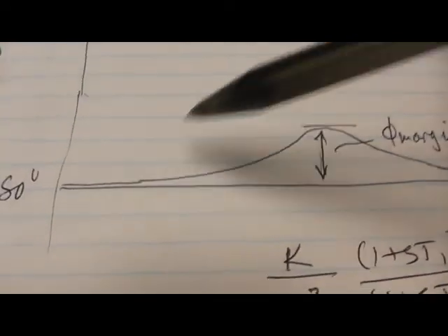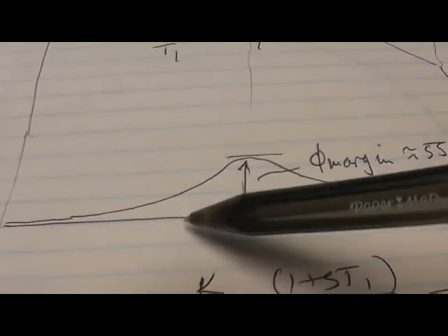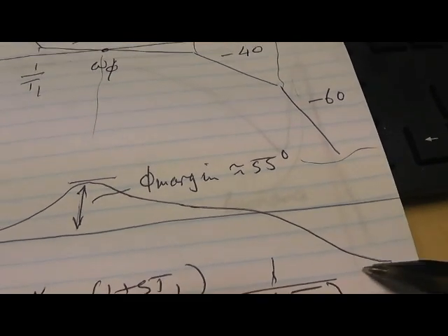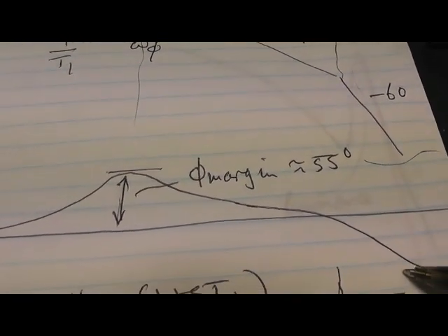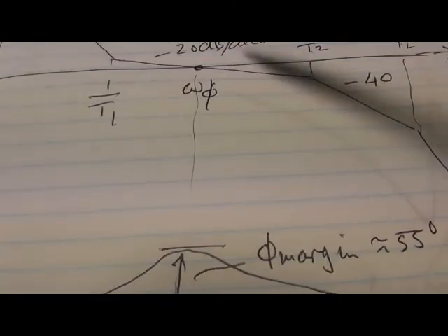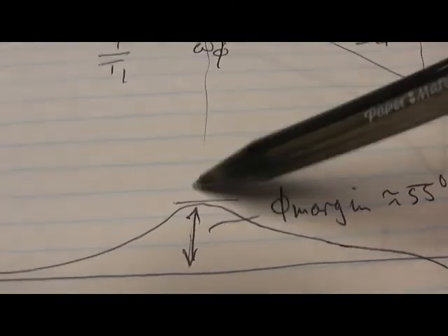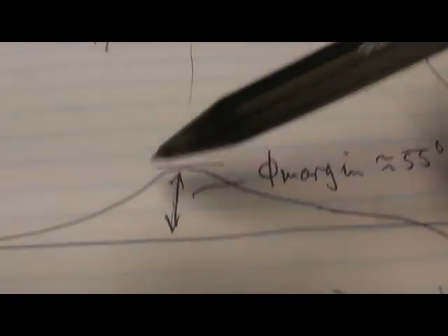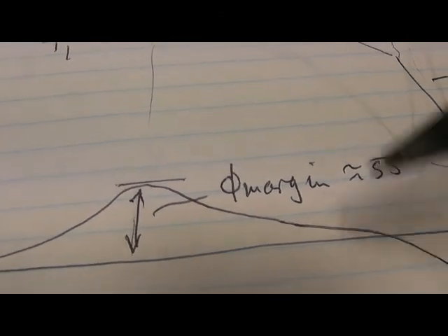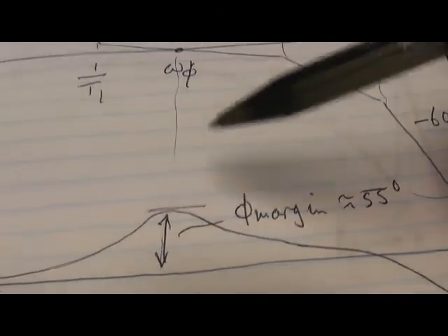And sure enough, the phase starts at minus 180 here because of the double integrator, but then the phase advance takes effect, and up it goes, back down again, and then after here it's pretty rubbish, but we're not too worried about that. That's this pole pulling it down. But as long as we've got one unity gain crossover here, and we get this phase which is much greater than minus 180, so it'll be minus 140 or something like that at this point, then we'd be happy.